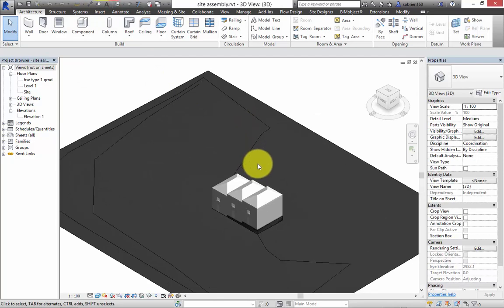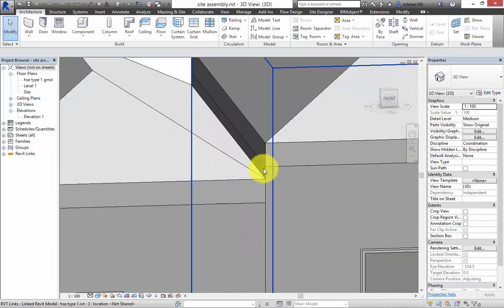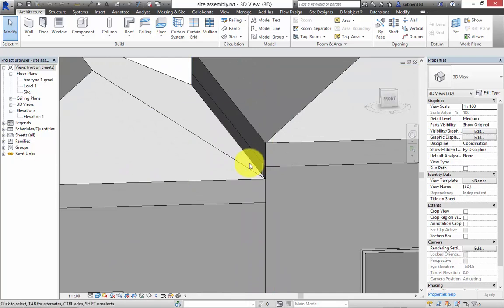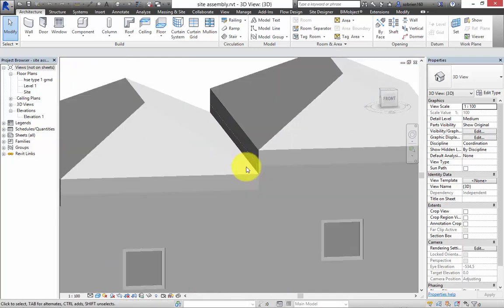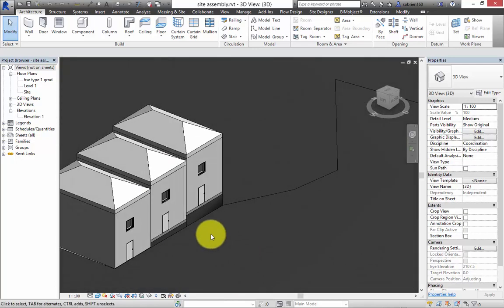Of course, you have some issues in here. Like, for example, if you're building a party wall, you have a point here where it's suddenly exposed to the open air because it's not insulated. So then you have to make a special design for those little corners, depending on how the difference is between how you step it. Does that make sense?